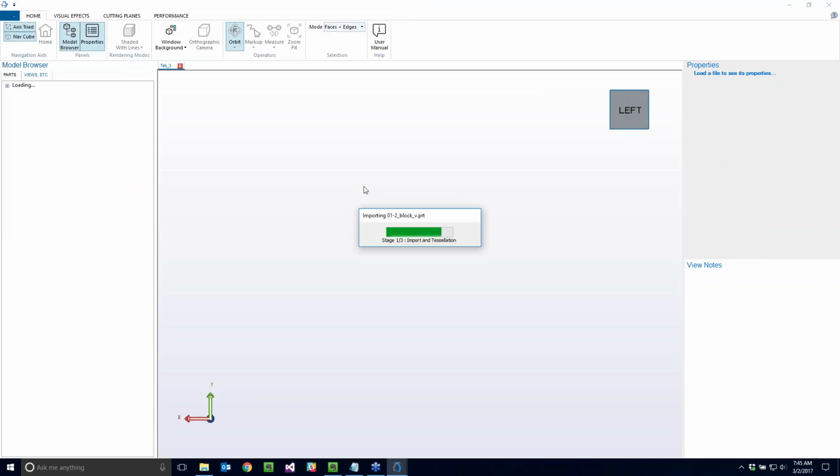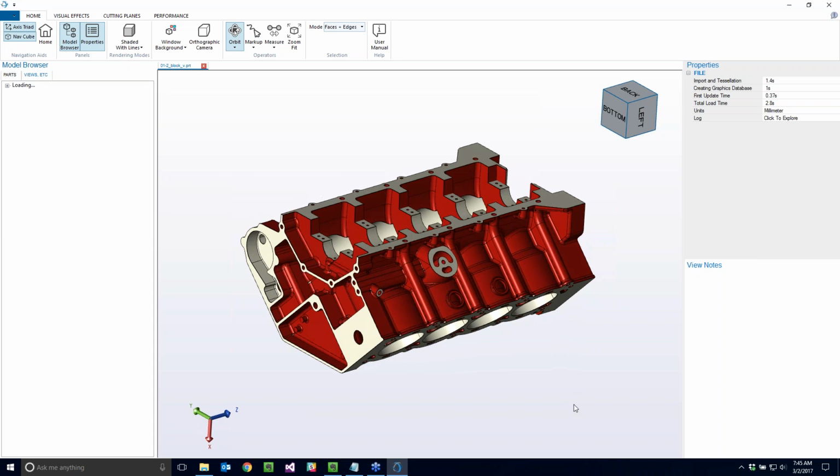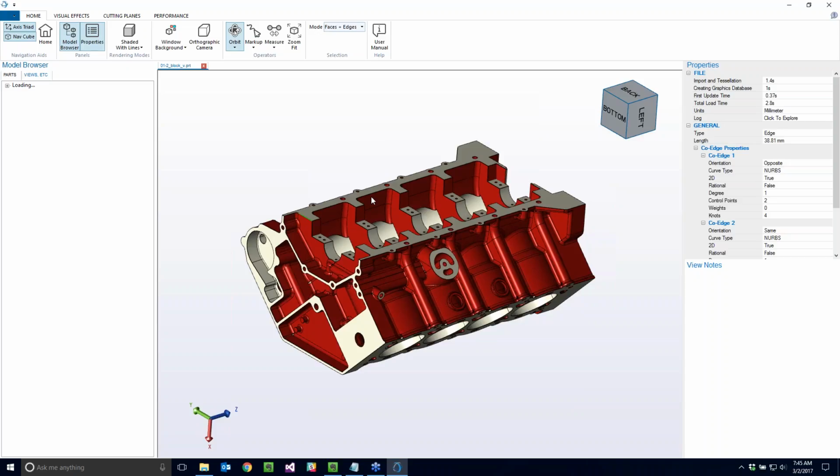Moving a little bit further, we'll look at a different model here. This is a Pro-E model, just a part of a much larger assembly. When we are able to read this data in, I can select a particular edge and get the associated data from the CAD file with that. So that might be persistent IDs, the actual surface area of a particular face, any material information or naming of that particular part. So having that selection, and then also the callbacks when you develop an application to go back and get that original data from the CAD file is very important.